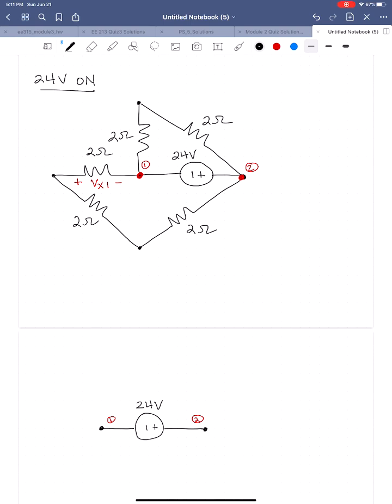So if we look on the up side, let's say, north side of that voltage source, we have these resistors, okay? And they're in series with each other, right? Because at this point, we only have 2 connections. So we're going to have 2 in series with 2. And so that's going to give us a 4 ohm resistor on the north side. And I'm going to box this up a little bit so it doesn't look so triangular. So this is going to be 4 ohms that reflects that 2 plus 2 ohms on the north side of that voltage source.